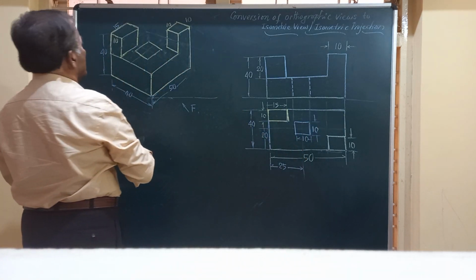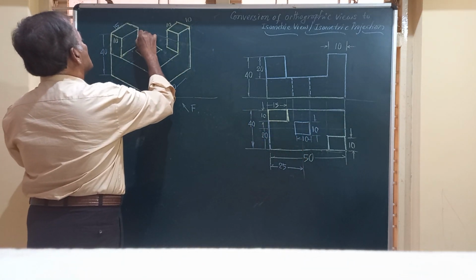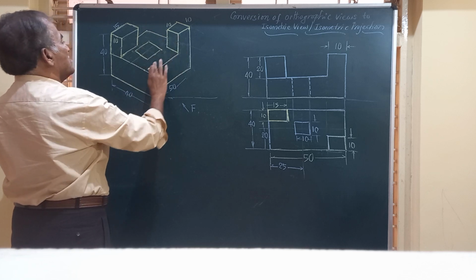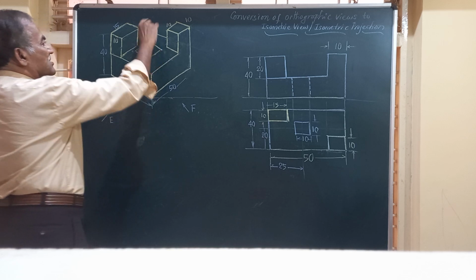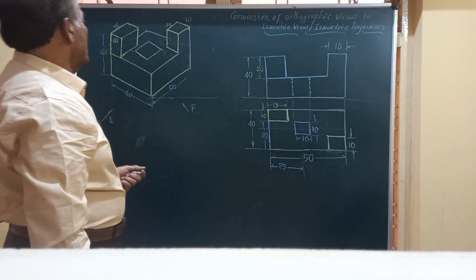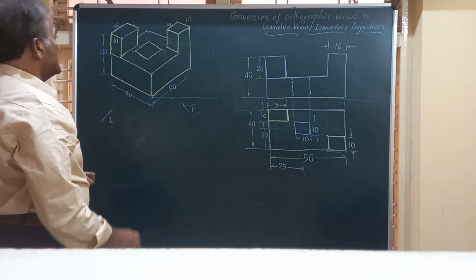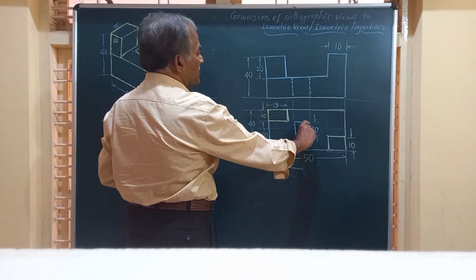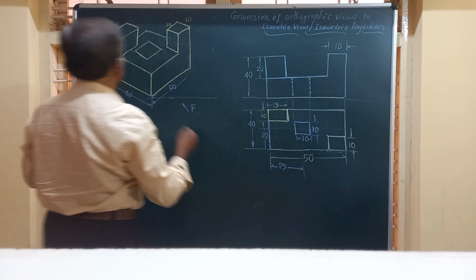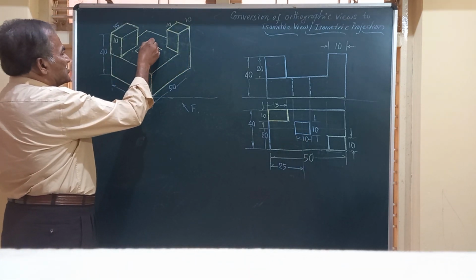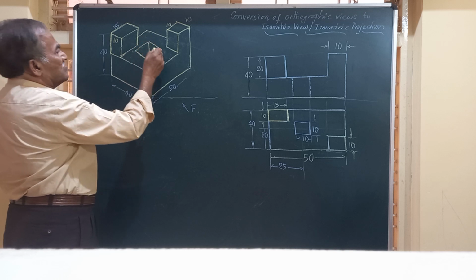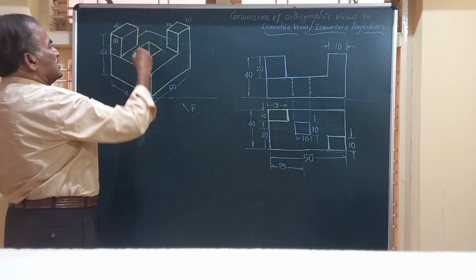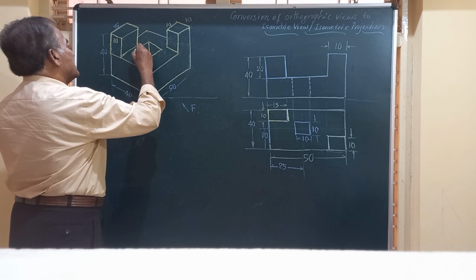They are visible. Hence friends, I am going to show this top face. So till here I will write down. Friends, this will give you the top surface of this block. And friends, slot I have shown. Friends, you can see here the thickness of this is 20 and this is only 10 by 10. So friends, we can just draw a vertical line through this slot, a vertical line through that till it touches here. So this will represent the corner or the vertical edge of this slot.